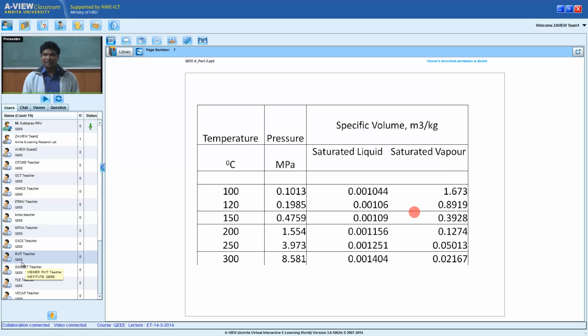And you see, when the pressure becomes 5 times, the volume is 0.475, nearly 5 times less. Now you see 1.6 by 0.4. So the pressure ratio and volume ratio of the saturated vapor are almost the same. Whereas the liquid hardly responds. Liquid volume doesn't respond to the pressure, that's why it is called an incompressible fluid. Saturation temperature responds marginally, whereas the specific volume of the vapor responds proportionally. Can you believe the same substance and three different characteristics behaving differently?